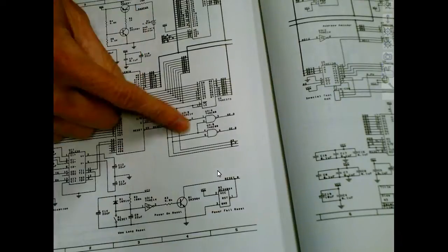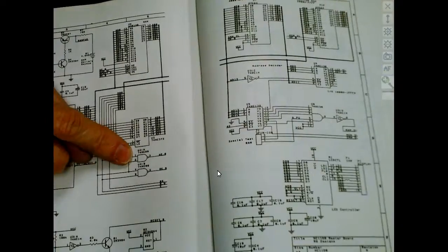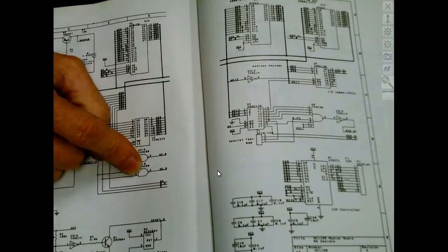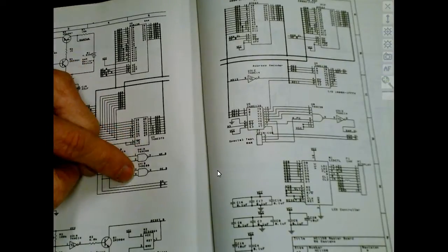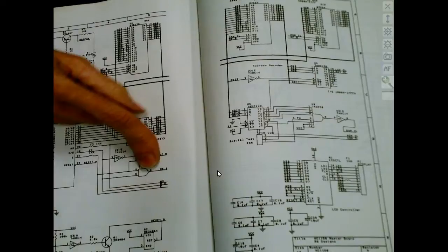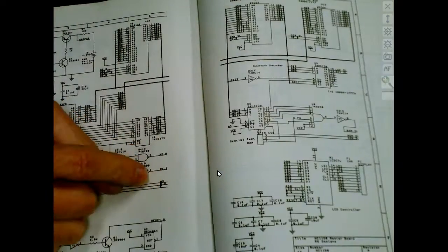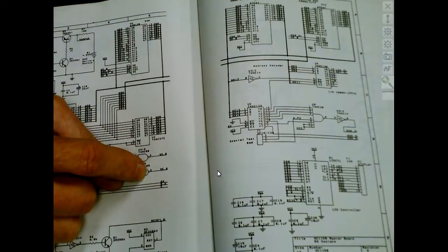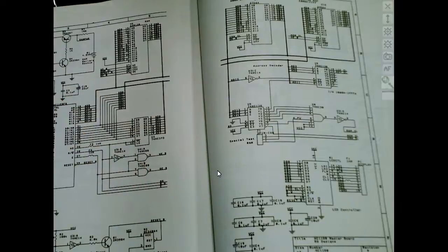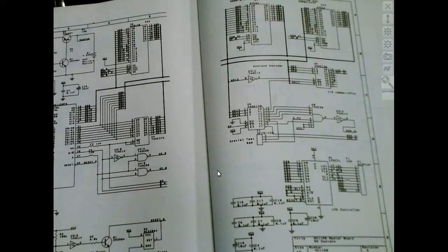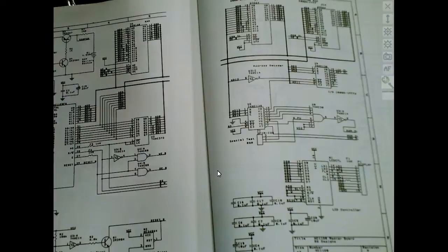But what I wanted to show you, even though we got off on a tangent here, is that these are drawn as NAND gates. Why? Because they're looking for all highs to get a low. So whatever's down this line right here needs a low for it to be true. What we're saying is that we have two symbols for every gate: a negative logic symbol and a positive logic symbol. What determines which symbol you use depends on what function the gate has in the circuit.